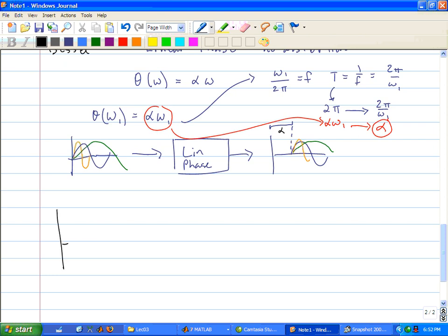I was trying to amplify these action potentials that come from brain cells. And as it turns out, the actual shape of that action potential is very important. And I want to make sure that I preserve the shape of the action potential as it goes through the filter. Well, if I use a Butterworth filter or an elliptic filter, there's no guarantee that after I filter it, that action potential is still going to have the same shape.